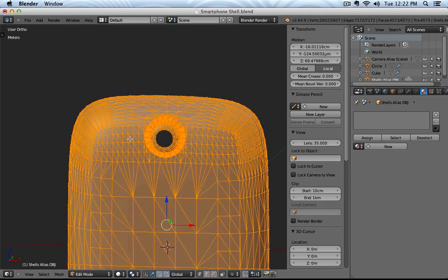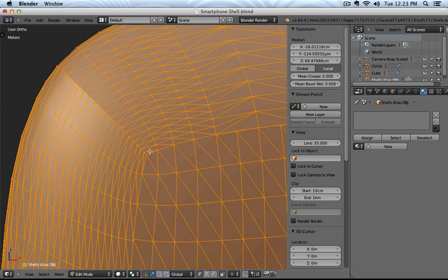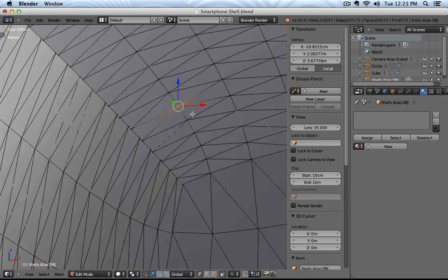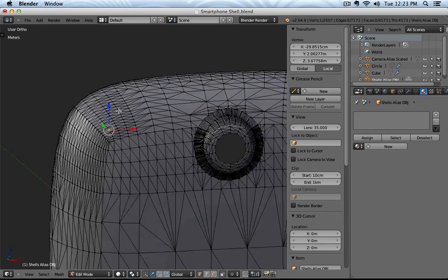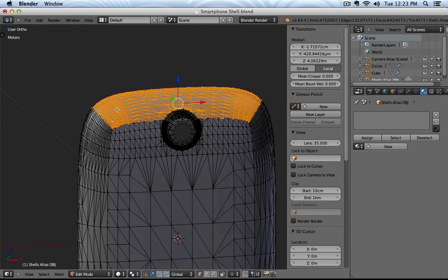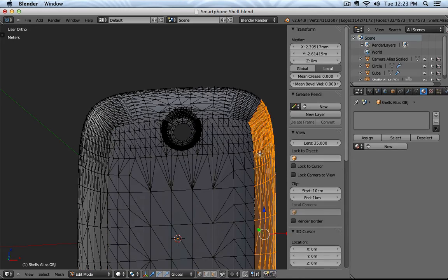That happened because Alias took basically all those NURBS patches and for each created a polygon mesh. So I can, for example, put my mouse onto here, press L, which says select all the polygon points that are linked to that mesh, and you can see that those are all still individual meshes.